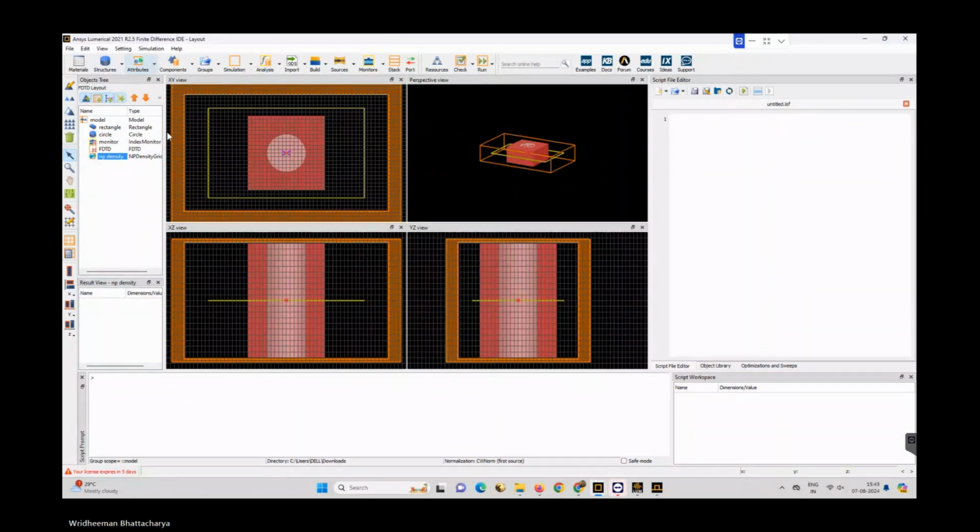Similarly, this temperature is of the heat solver, how that heat one is operating. The LC orientation is basically the liquid crystal orientation. If the orientation of liquid crystals differs, the properties change. There is an example in the ANSYS application gallery of a liquid crystal layer on a ring resonator. It acts as a cladding on a ring resonator, and shows how that liquid crystal shifts the transmittance graph.